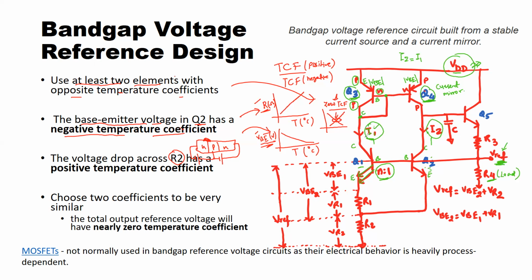I have this voltage, which is VB here, and then VDD minus VBE. This is VBE, VDD, emitter to base. So I have some voltage at the collector of this transistor, and I have voltage at the collector of this transistor, assuming that they are at the same potential.